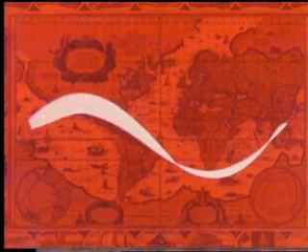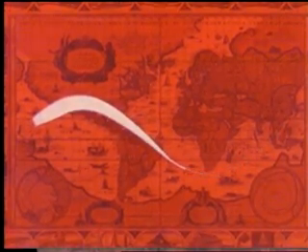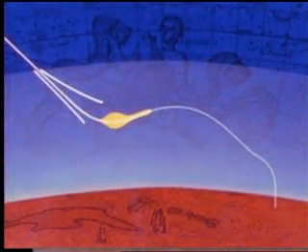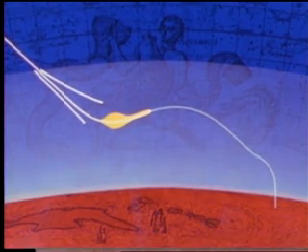During the first critical 70 seconds of this control period, the initial landing footprint, 20,700 miles in length, will be shrunk around the target to this 2,070-mile footprint. In the remainder of this first control period, the footprint will shrink further to this 690-mile-long area. The first control period is followed by the controlled skip.